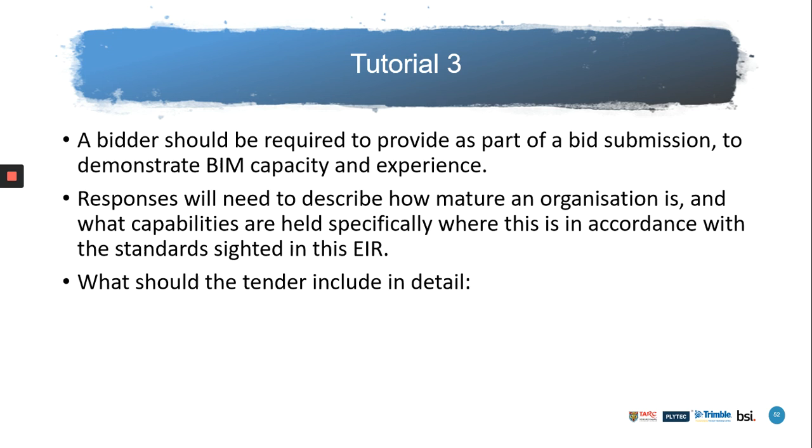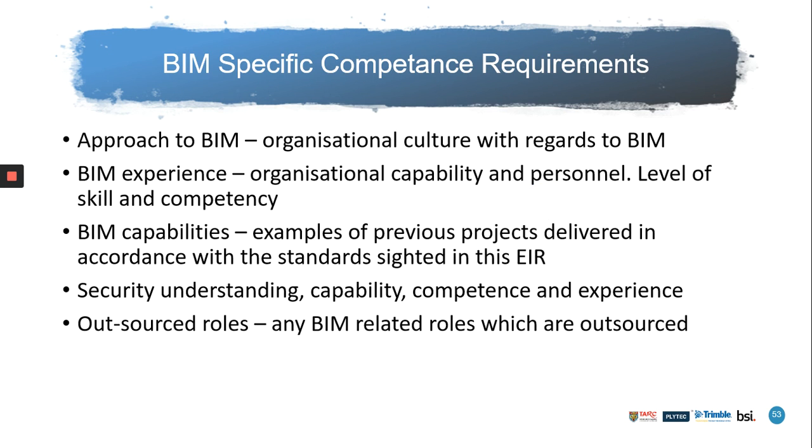So what should the tender include in detail? The BIM-specific competence requirements: they'll need to know the approach to BIM, what the organization's culture towards BIM is, their experience in BIM, their capability, their security understanding, and if there's any outsourced role when they are dealing with BIM.